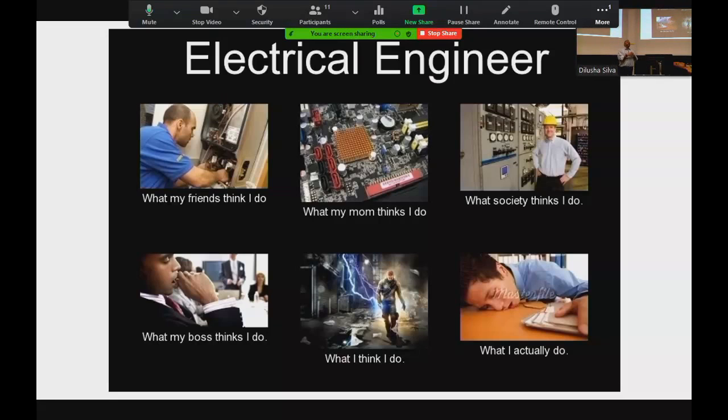Fuses are far more forgiving for load fluctuations than circuit breakers. Yeah? And the nice thing about a fuse is when you've got a problem and the fuse blows, you have to go there and fix the problem. We do suffer a little bit of people going back and resetting a circuit breaker and going, yep, that's held, the problem's gone away, and not really fixing it. So I grew up in the era of fuses, so they do have their uses, definitely, right? But they tend to be high rupture scenarios, high voltage, high currents.